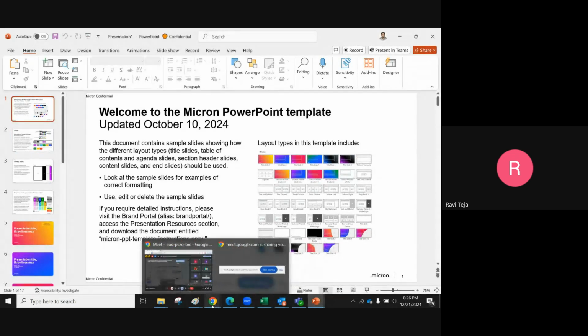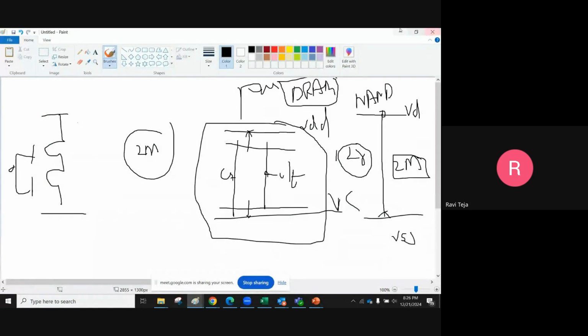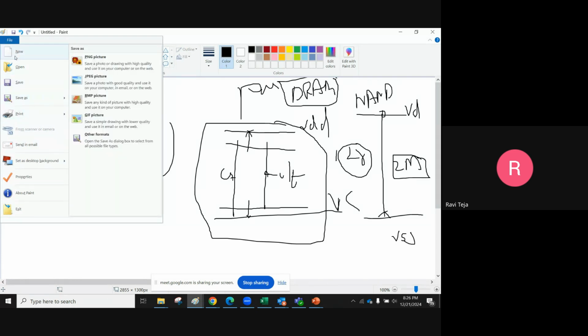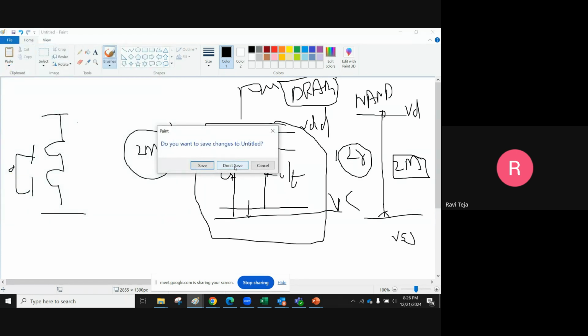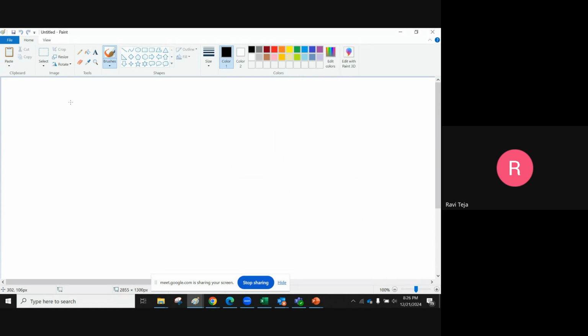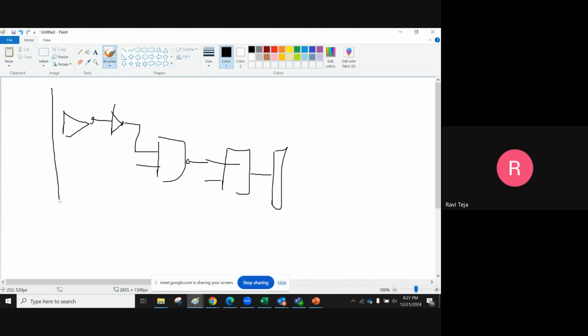So for that reason, I will build the digital cells in a standard height. What does standard height mean? Imagine I'm using a circuit with some inverters, and then some NAND gate, and some muxes, and then some combinational logic circuit.